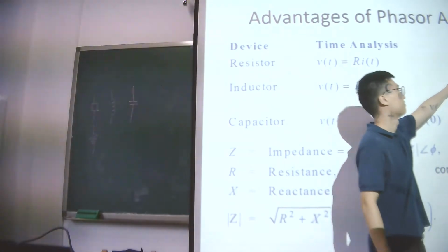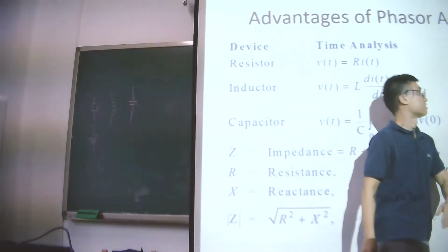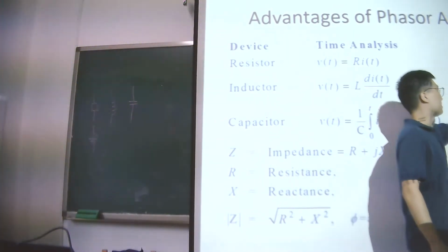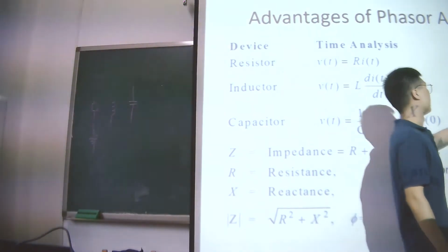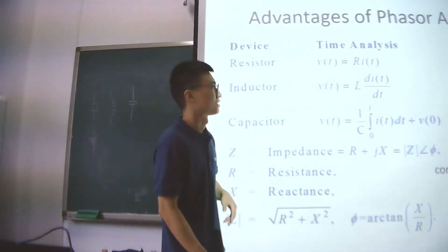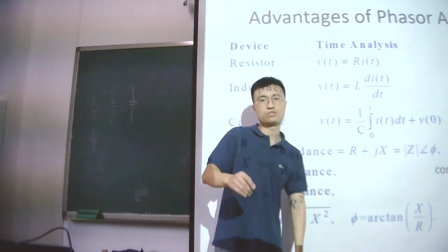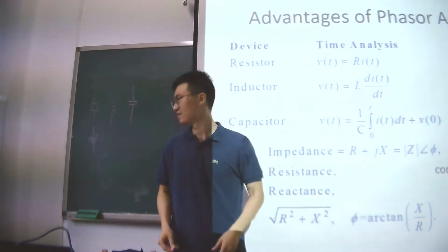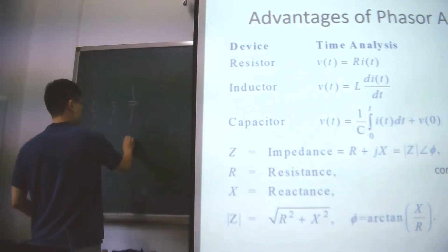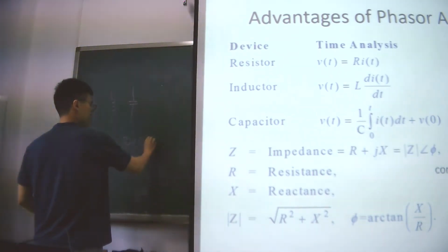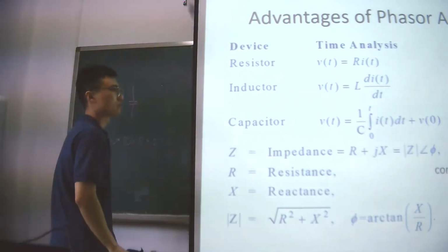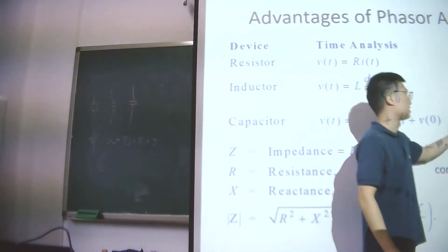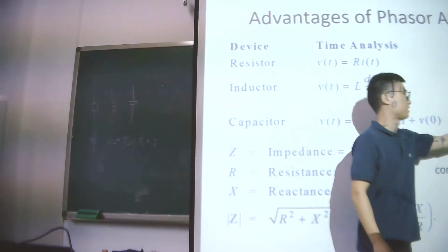It's quite easier. The voltage and the current and the resistors, right? Inductance and capacitors is the value of this inductor and capacitors. The omega is 2 pi multiplied with the frequency, right? This is the omega, right? So you have to use these phasor calculations to calculate the voltage. This is the relationship between the voltage and the current.